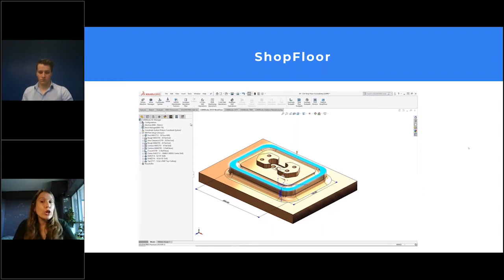You know, you could generate setup sheets for them. That's a functionality in SOLIDWORKS CAM and CAMWorks, and the setup sheets are great. They can accompany your G code file, and they're static documents, but they'll help the operator know information about how to set up the stock or the machine, the controller. It'll give basic estimating time, part material, and so forth. But they're pretty limited otherwise in the CAM and CAD data that they can see.